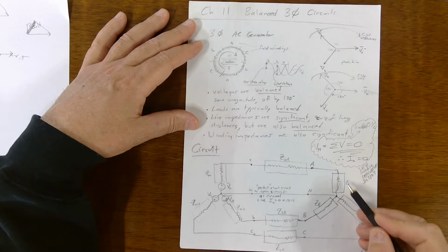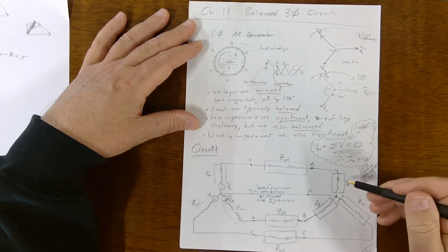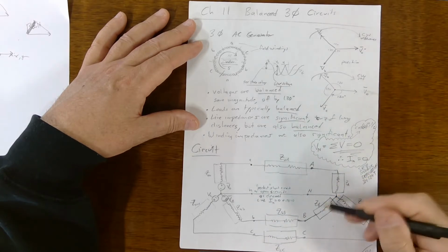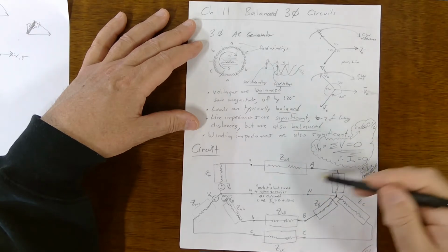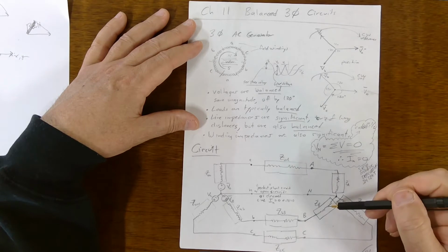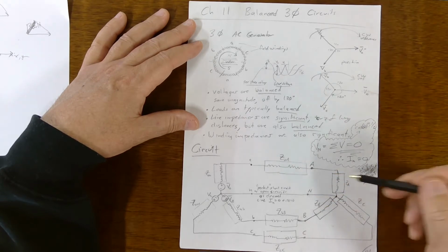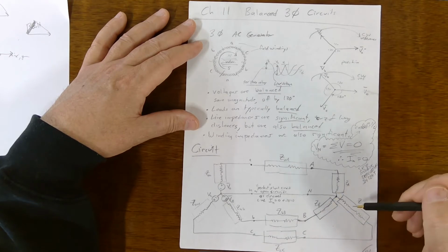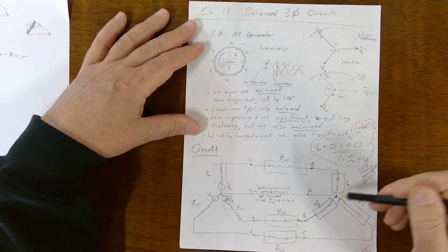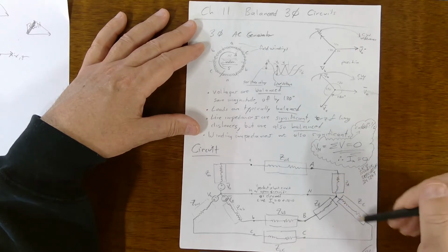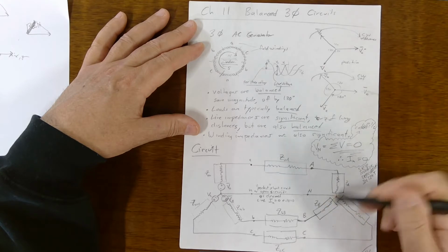And then it's connected to a load, right? And those are typically 3 loads, and we call this a 3-phase load. It could be one machine with 3 parts in it. It could be a really big motor with 3 phases in it, or this could be a model of a much more complicated distribution grid where we just abstract it down to these 3 pieces.